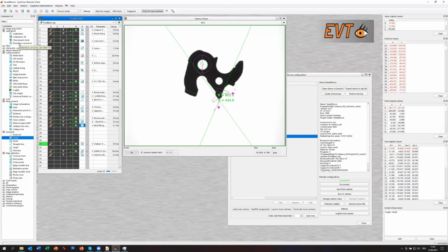Of course, depending on the smart camera, maybe you don't have a very good lens, so distortion correction for the lens might be really good. The tool is here. Of course, this is an area tool. You will see if you use it on a smart camera, with not so much computational power, it's not the fastest, but it's still here and it works. If you have a good lens, you can use the simple calibration tool, which does a simple scaling factor calibration, and it fits, and then you get real world coordinates for that. This is at the end exactly the same if you want to do robot vision, for example.